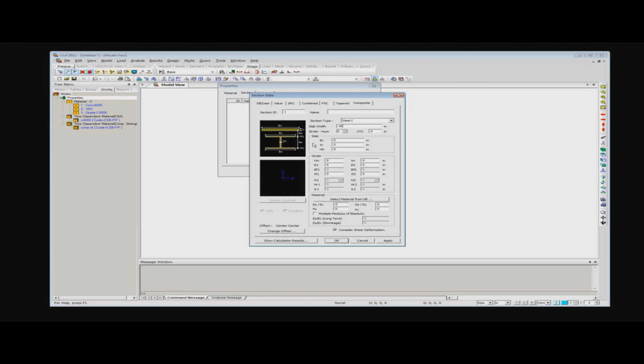Going to define this. All right, the total width is going to be 450, and we're going to have 4 girders in total, and the distance center to center is going to be 102 inches. Again, here we're defining the slab for only this section, so it's 102, and the thickness of 8 and height of 1. Okay, and now here defining our girder.